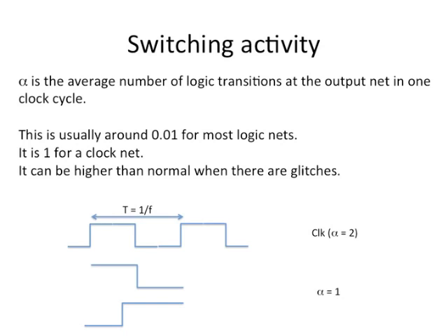And as I said, alpha is an average number. It captures the average number of transitions in a clock cycle. Sometimes people call it the probability of transition, but as you saw, the alpha value could be more than 1 if there are a lot of glitches. So in that sense, probability is not the most accurate term to use. But most of the time alpha is less than 1, and in fact for a lot of the data paths and nets, the alpha value is less than 10%, perhaps even less than 1%. So that is what the typical alpha numbers are.